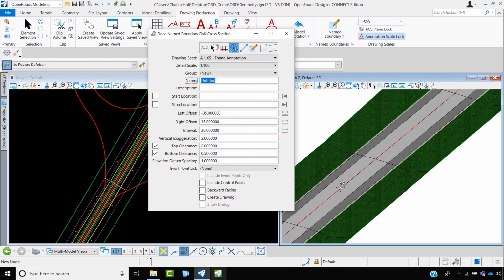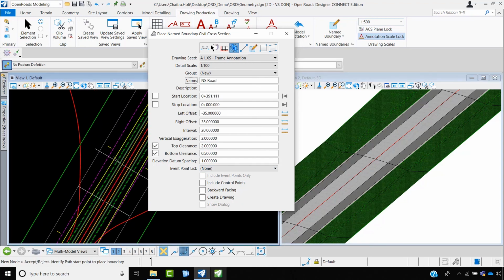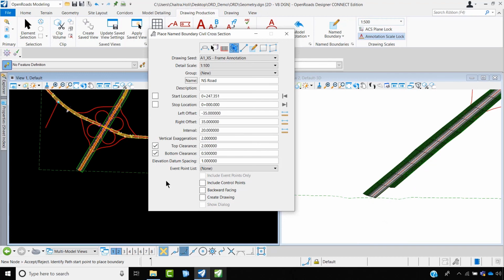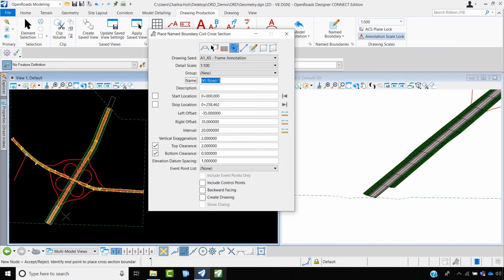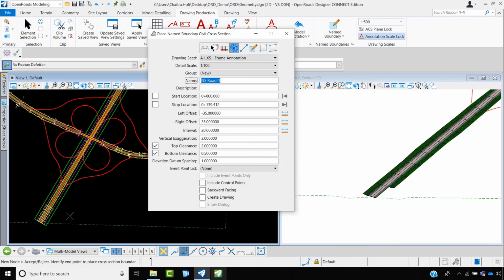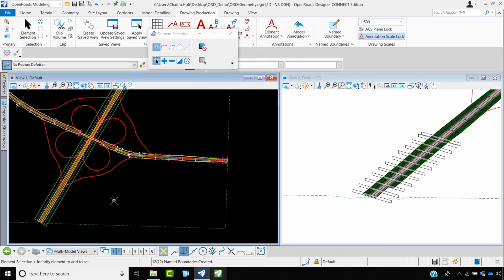Okay, selecting plan. Select the changes. Let us say do not select much. I'll just select at least some of the things up to this change and select this. You would notice that it is cut into slices in 3D views, that many numbers of cross sections at every 20 interval over here.